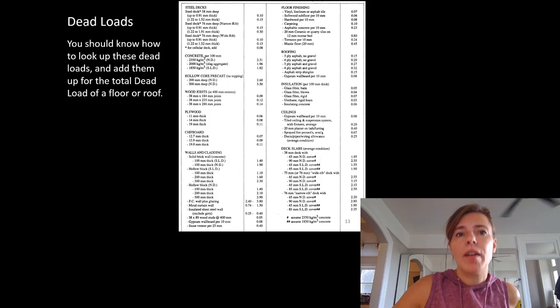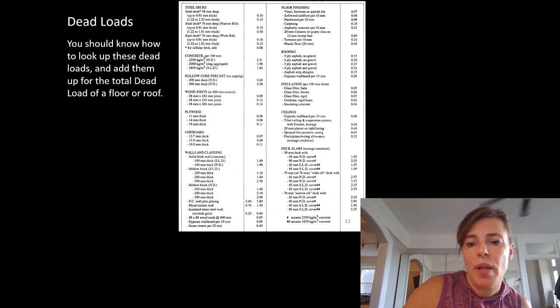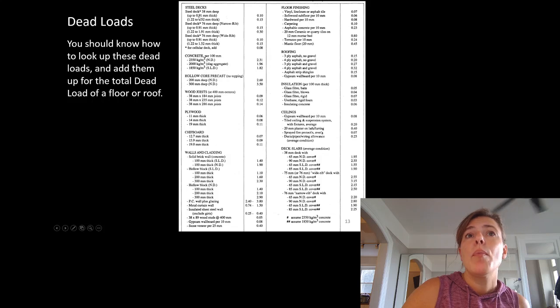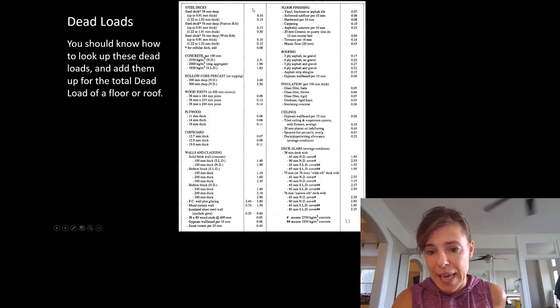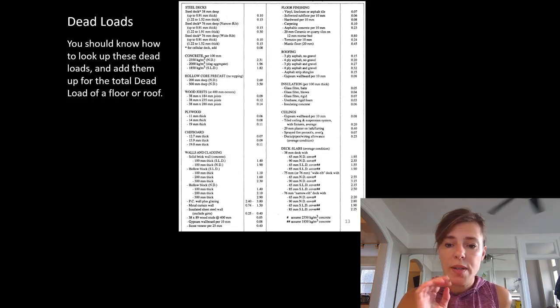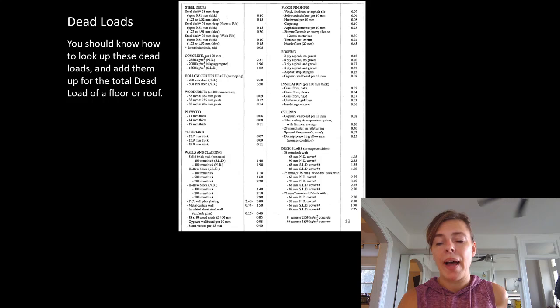You can see here, I'm going to have to lean forward, so I apologize for getting closer to the screen. But you can see here, steel decks. Steel deck, 38 millimeters deep up to 0.91 millimeters thick. This is the norm. Unless I tell you otherwise, this is what we're talking about. 38 millimeters deep, 0.91 millimeters thick, or 0.1 kPa for our metal deck. So if I say, what is 38 metal deck? That is what I'm talking about.